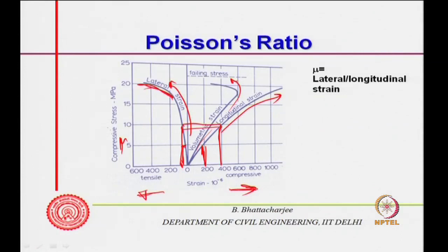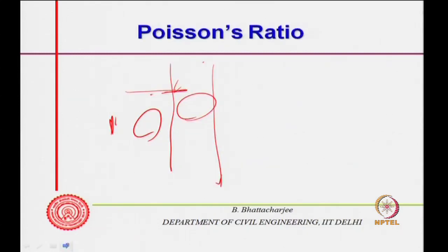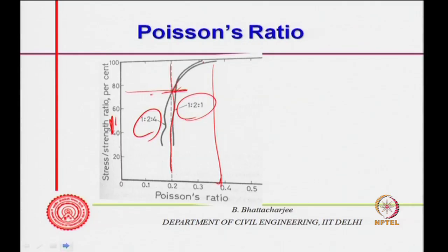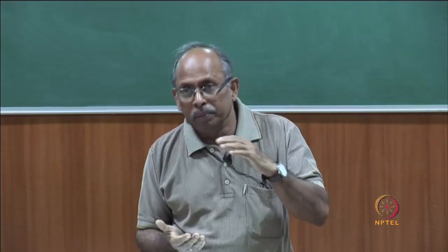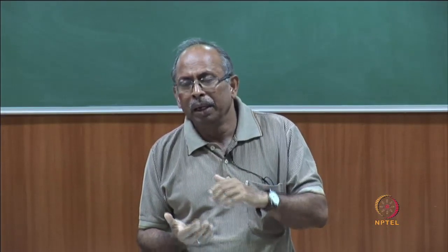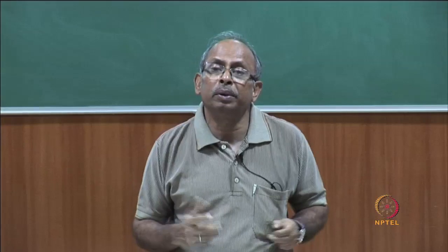Suddenly the lateral strain is increasing; here it was increasing in a slow manner, but it started increasing in a faster manner. This one is almost close to linear, with slight variations, but it increases at a fast rate, and this increases at a still faster rate. We can understand this from the physical scenario, because micro cracking would result in a lot of transverse deformation. Longitudinal deformation would also be there, but lateral deformation will increase significantly because of the micro cracking.